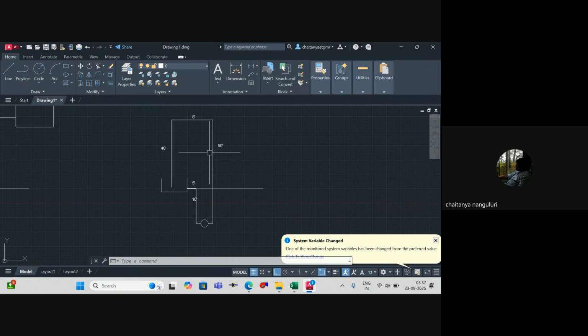See, because the pump has to do the additional work. Because what is the pump work done? It's the pressure difference between inlet and outlet. You agree? So at the inlet, you already have higher pressure there, which is 10 feet. So at the outlet, because automatically it's 10 feet, the additional work, whatever it happens, is after 10 feet you're putting. Understood or not? So that is basically your static head. So here the answer is 40 feet.